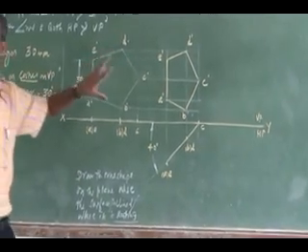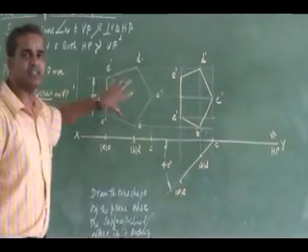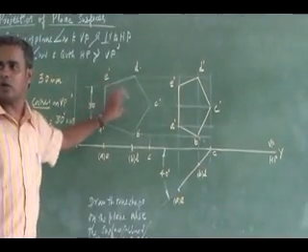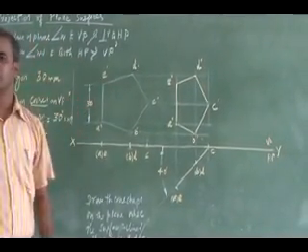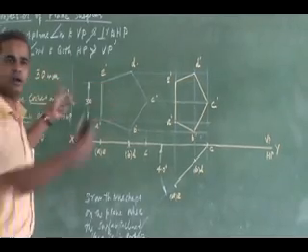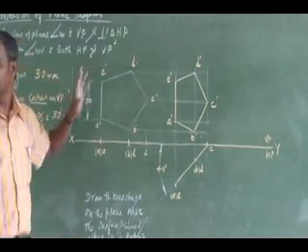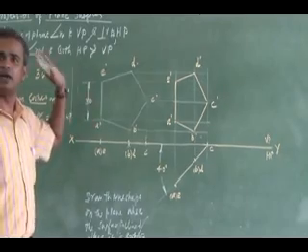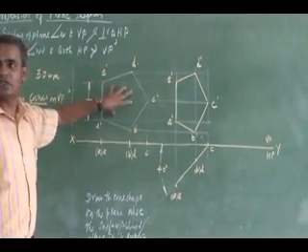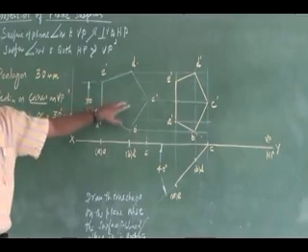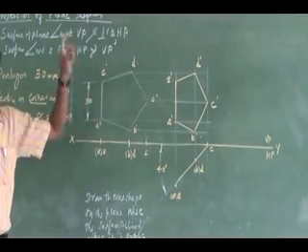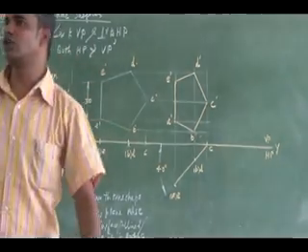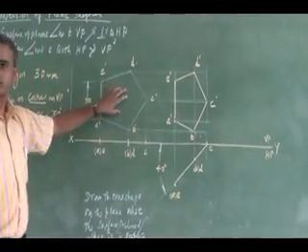And if it is a hexagon, in which orientation do I have to draw it? For a pentagon, you have only one orientation. For a hexagon, if it is resting with a corner, the corner has to come on the right side. If it is resting with an edge, I have given two orientations. So it depends upon the problem how you have to draw it. On which plane you draw the true shape is very essential, right? So draw the true shape here.